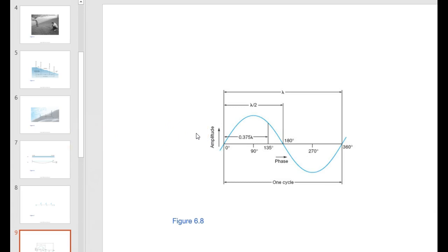And that's actually what the computer in the total station does. So it bases it not on distance is equal to rate times time, but rather on distance is equal to some full number of wavelengths plus this single partial wavelength, and it does that 7 different times. So the distance is going to equal n1 times lambda 1 plus this partial times lambda 1, n2, and so forth, until there is a unique solution that's arrived at.